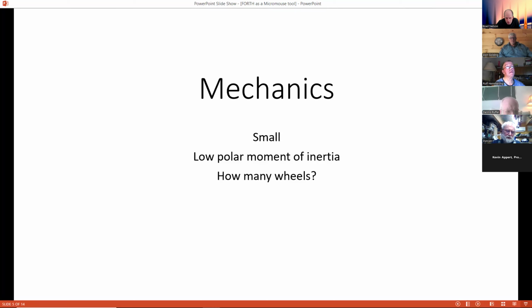At least one mouse uses six wheels at different heights. It balances on the center wheels during turns and settles onto four wheels during acceleration and braking. So it's either tipping backwards during acceleration onto those four wheels or tipping forwards under braking onto those four wheels. And hopefully in the turns it's balanced and it's a two-wheel mouse. Three or four wheels that are independently steered and driven has been done a few times. It's quite amusing, but unlikely to be fast.